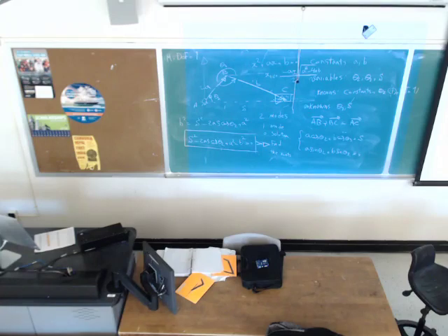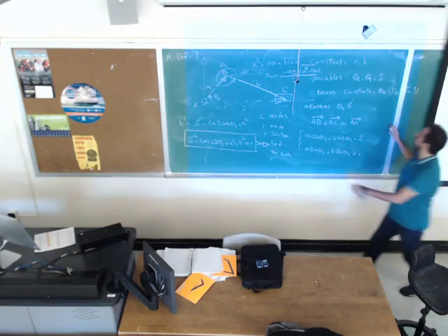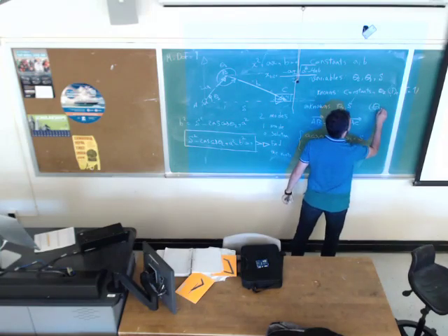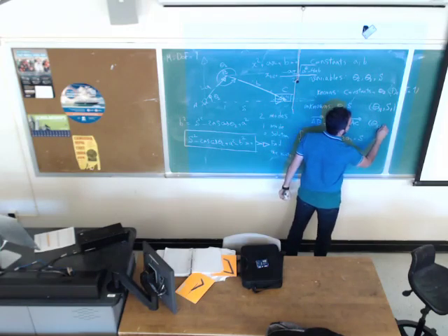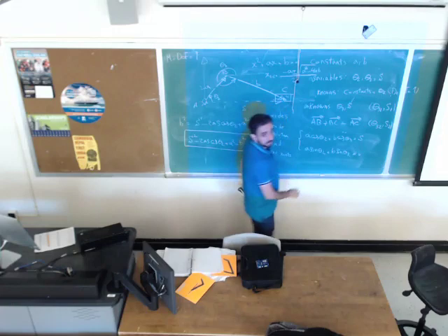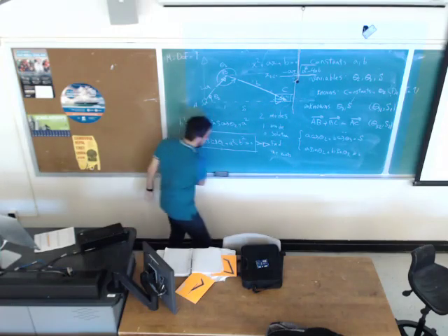The outcome of this is one theta 3. I will call it theta 3,1, the angle of theta 3 for the first mode. Now plug in S2, the second mode. Plug in S2 here, find another set of 4 angles, and find theta 3,2. Then you have to report this: theta 3,1 and S1 for the first mode. If you have a second mode, theta 3,2 and S2. Mode 1, mode 2.